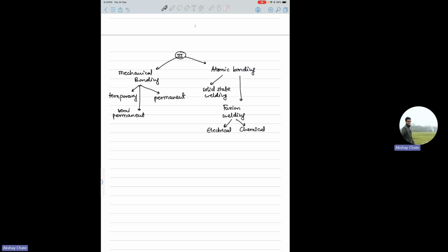And then you have solid and liquid state. So there will be separate, distinct solid plus liquid state welding. So the difference is in the solid state welding, this first category, there will be only solid state. In the fusion state, there will be mostly liquid melting kind of thing. But here you'll have both distinct phases, and that happens in your brazing, soldering, etc. So brazing, soldering,